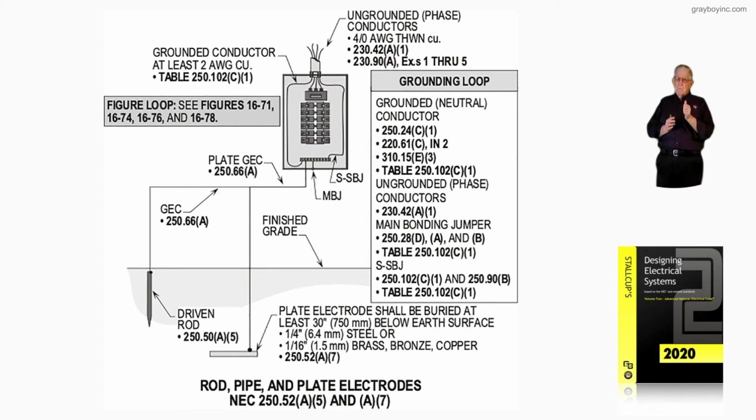Most inspectors go along with this concept. If it's 51% or higher, then they're saying, okay, the neutral's current carrying. As an example, L1, L2, L3, 100 amp neutral load. If 51 amps or more is harmonically or non-linear loaded type neutral, then it's considered current carrying. The 50% rule, now you can get a better handle on that in 400.4(A).